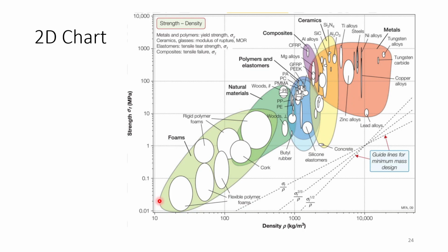Now these are the Ashby charts, or known as 2D charts. In this case you draw two different properties as two axes. So here density and strength are plotted. So here you find various bubbles according to the category of materials. For example, you will be finding a ceramics category, polymer category. So all polymers will be having strength very near to a particular range and density particular to some range. So then you will be finding out some bubble.